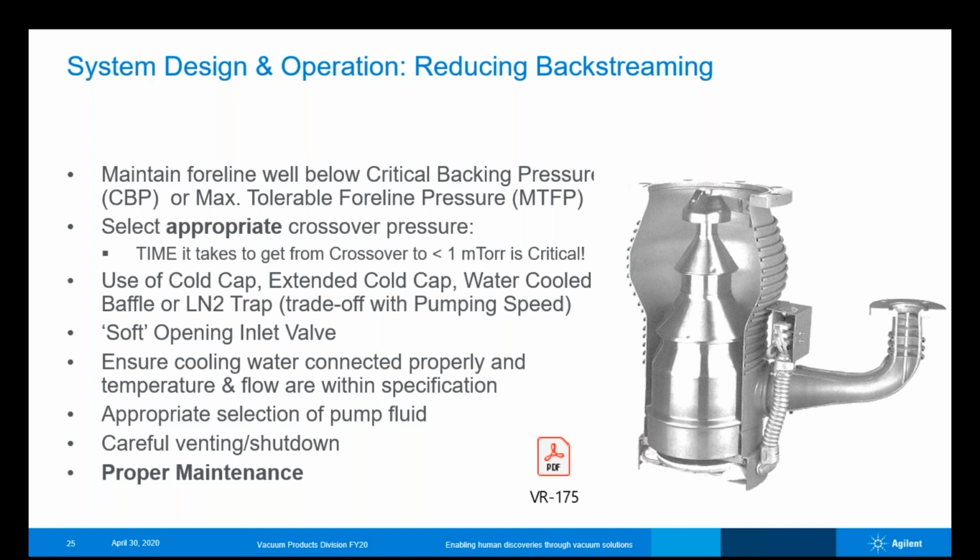Careful venting and shutdown. There are things like cold loops inside some of these pumps that will rapidly cool down the oil when they're turned off. Once we've stopped pumping, we want to get that oil to cool and go back into 100% liquid phase as quickly as possible. The less time that gas spends in vapor phase, the less chance there is of oil molecules wandering their way back up and perhaps contaminating our vacuum system.